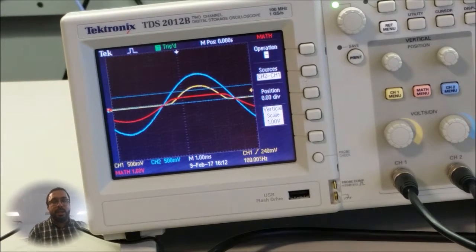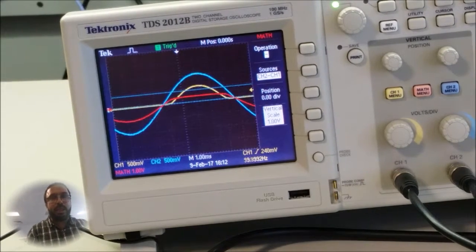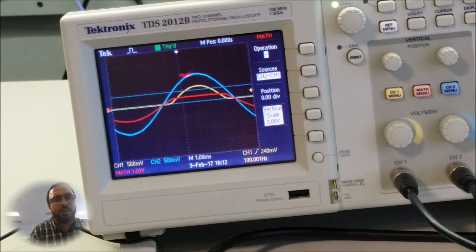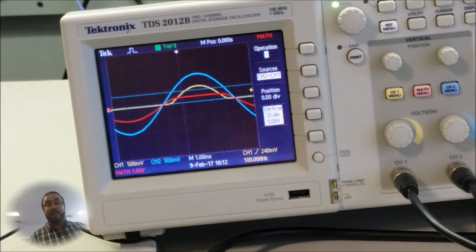Because the rectifier, or the diode actually, in this case, will not be on until the input voltage, which is the blue one, is above the barrier voltage. Very good. And what's the barrier voltage? It's actually the difference between the input voltage and the output voltage when we have an output current, basically. So when the diode is conducting.